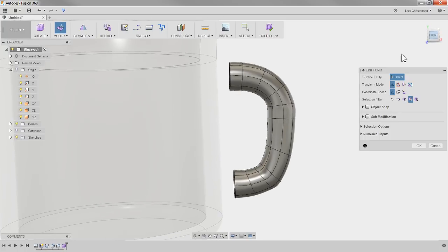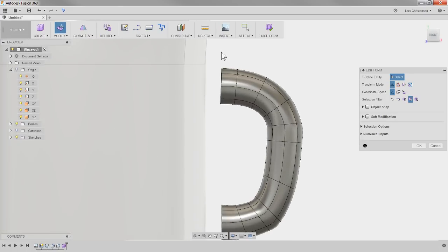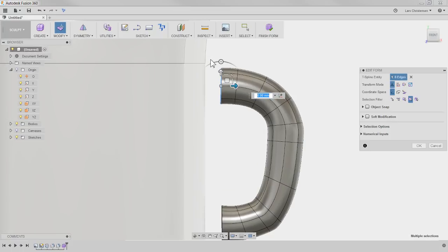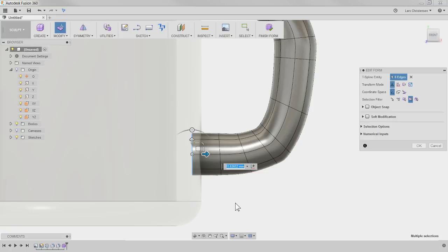Now there's a couple of different ways that you can get this combined with our coffee cup. I'm going to add one, I don't like how this one is not straight. There. I'm going to show you what I would call the surface way to do this. So I'm going to make another segment, and I'm going to let it go past my solid model a little bit. And I'm going to do that down here in this section too. Now, hold down Alt and drag a new segment and let it go into my solid model.